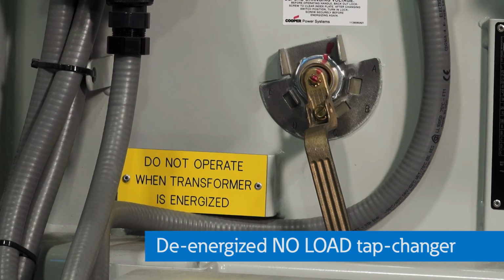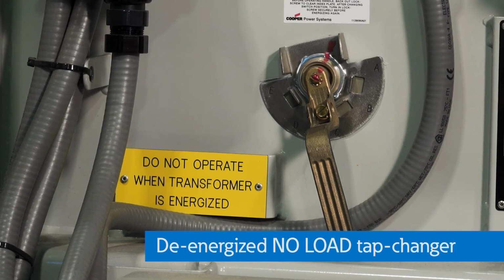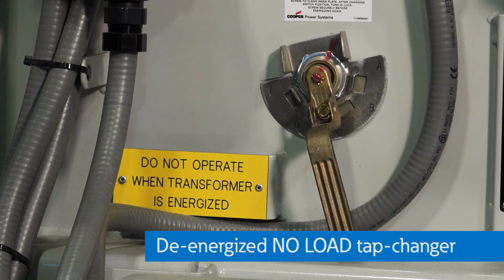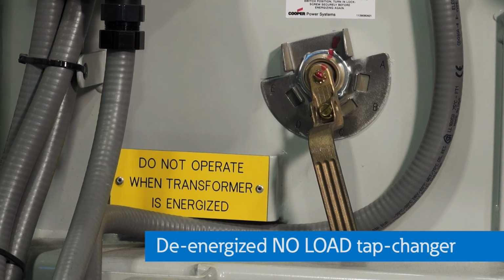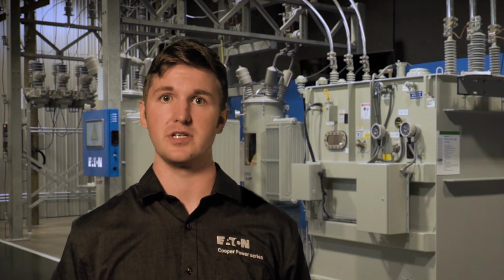The tap changer provides a means of changing the voltage ratio of a de-energized transformer without breaking the transformer seal. It is operated by means of a rotatable handle located on the side of the transformer. The tap changer is normally provided with 5 positions, as indicated on the tap changer dial plate and transformer instruction nameplate. This allows for a 2.5% or 5% increase or decrease in the voltage.